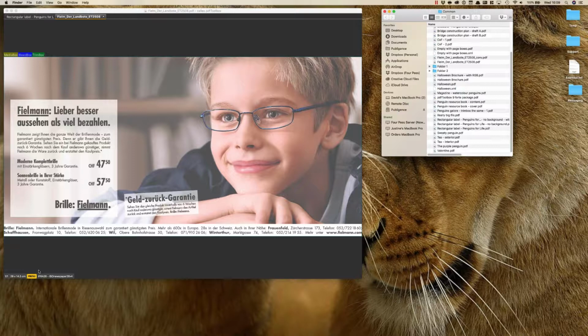This badge appears because the PDF file claims to be a pdfX3 document. We have not done preflight at this point, so the only thing pdfToolbox is doing right now is looking at the document, seeing that there is metadata in the document that claims that this document is pdfX3 compliant, and then it shows us that this is the case here.